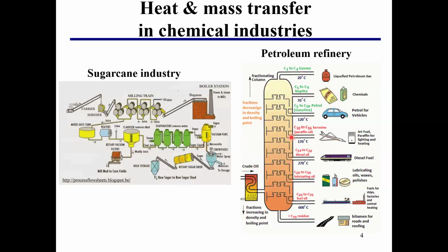So we just saw that vapor travels from bottom to the top, and the liquid travels from the top to the bottom. And as both of them are traveling across the distillation column, mass transfer also happens from the vapor phase to the liquid phase, as well as from the liquid to the vapor phase. Okay, so basically chemicals move from one phase to the other such that they tend to approach the equilibrium for that particular temperature.